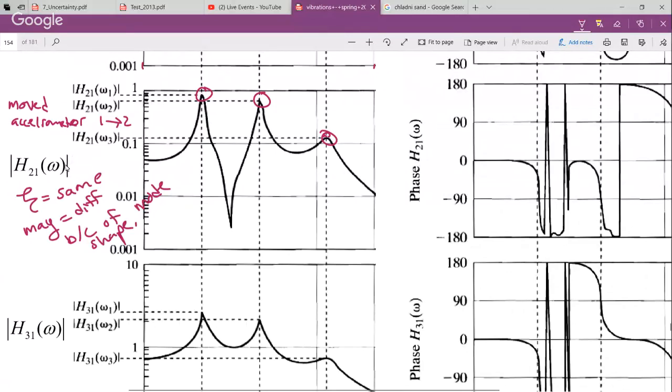We could have derived it, but I didn't. We looked at multi-degree-of-freedom vibration models, mostly in terms of mass, damping, and stiffness matrices. We decoupled them and wrote them in terms of natural frequencies and damping ratios. But there's another form of those equations we could have written: instead of mass, damping, stiffness, we could have written them in terms of mode shapes, and defined the frequency response from mode shapes.